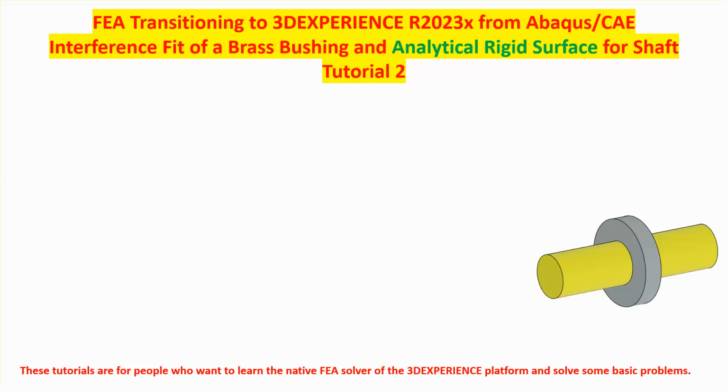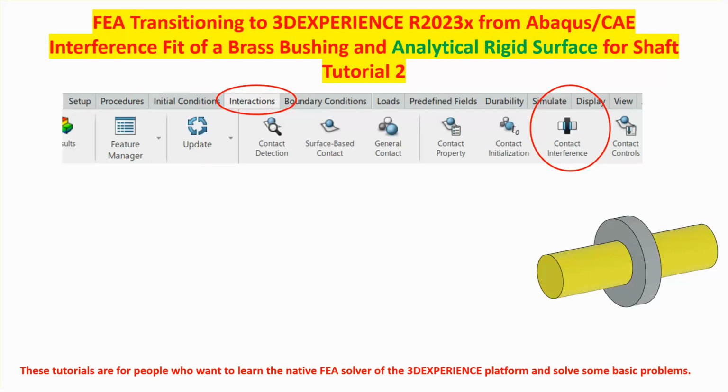So they are limited, although there are many situations where the surfaces are like that, such as punches, for example, etc. But if your surface does not meet those two requirements, you have no choice but to mesh it with either shell elements or solid elements, and then declare them to be rigid.